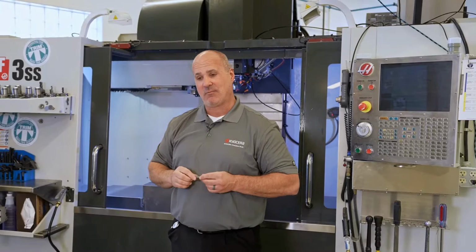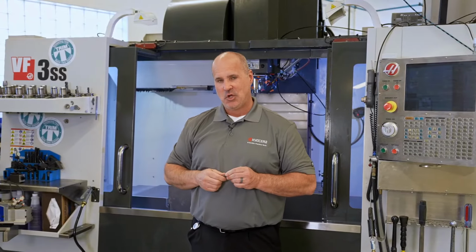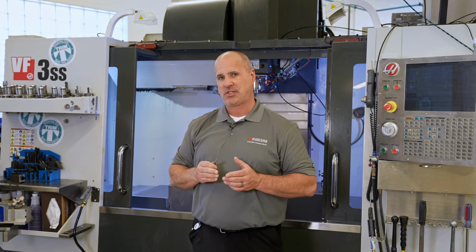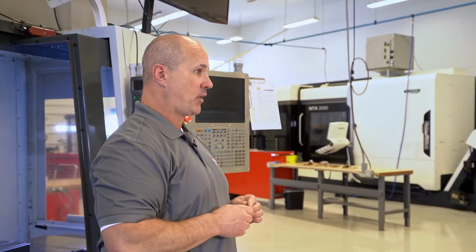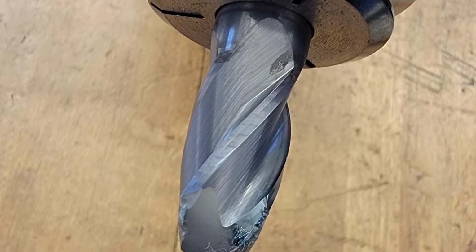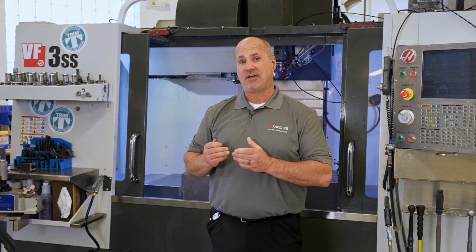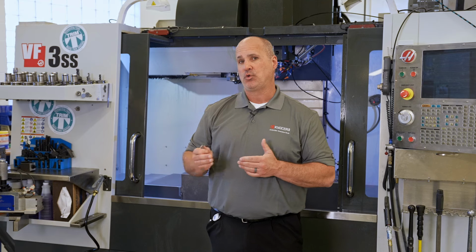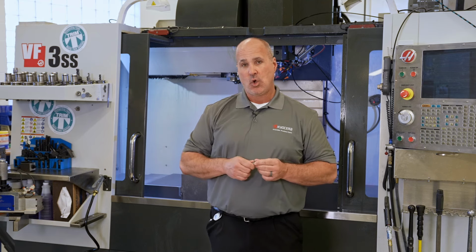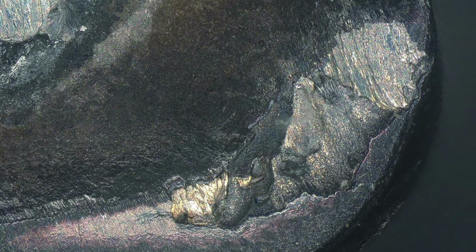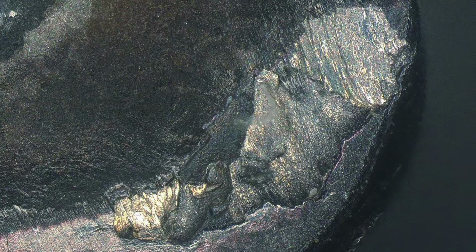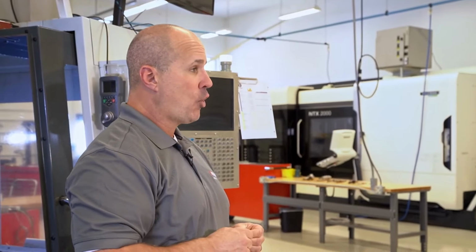We're at the scene of the crime and we have to analyze the evidence. We talked about speeds and feeds and the sweet spot in regards to tool wear, but it also can tell us a lot about damage in regards to the tool. For example, catastrophic failure on a tool is often a load-related issue, or a built-up edge is where there's enough heat to allow that material to weld itself to the cutting tool. Or we could end up with cratering, which is a thermal chemical reaction, again brought on by heat, or edge chipping that can be brought on by load as well.